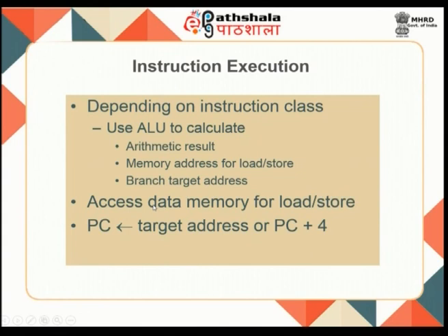So, all other instructions do not have to perform this step. For a load or store instruction, the effective address has already been calculated. So, using that effective address, you will have to access data memory. If it is a load instruction, then use that memory address and bring the data to the processor. If it is a store instruction, you already have the memory address, use the data that is available in your register, which is the data to be stored onto memory, and go ahead and finish your load.